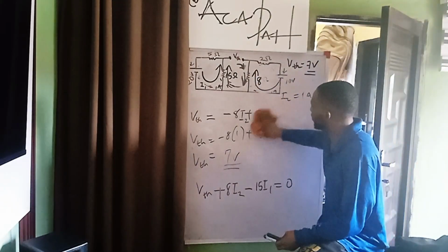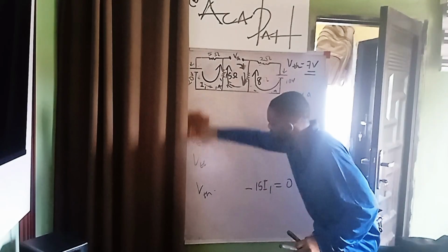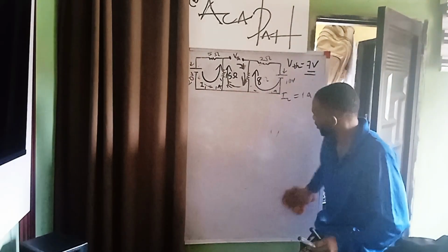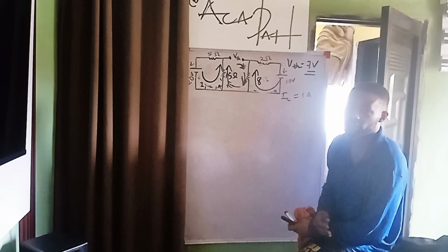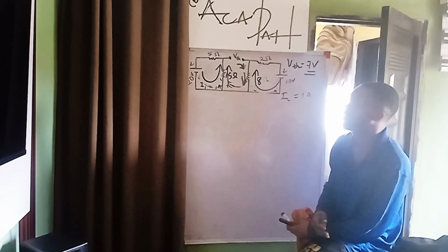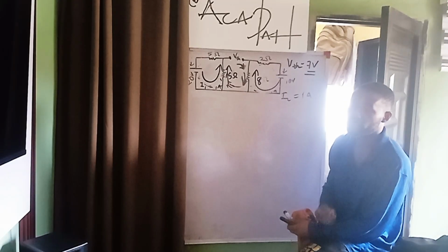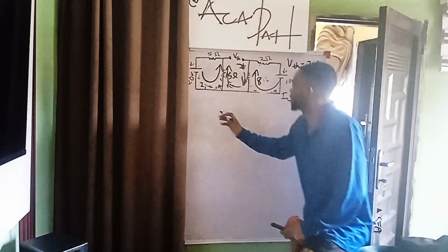So we remember that Thevenin's theorem stated that in a linear circuit or multi-complex circuit, the Thevenin voltage, the load resistance and the Thevenin resistance are always in series. So if I know that, let's put this in series.